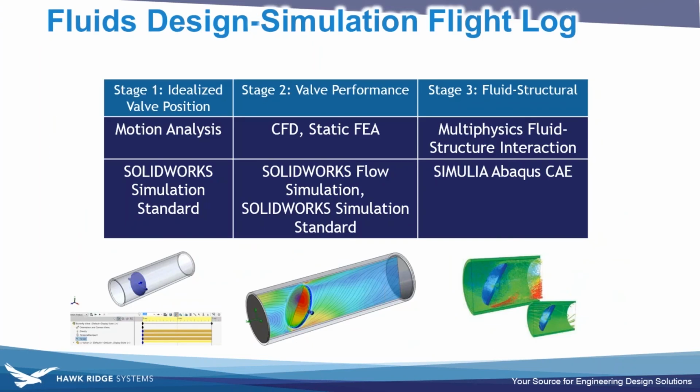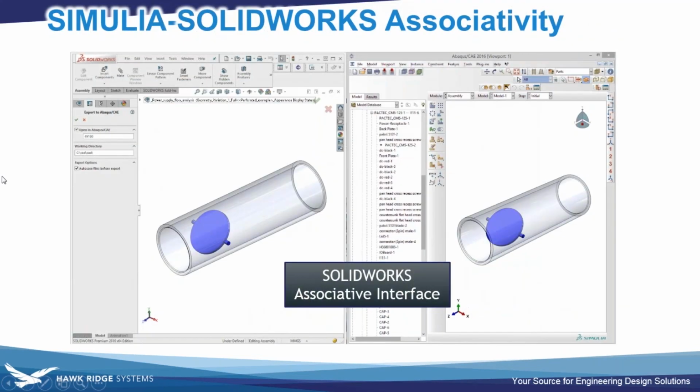And so in Abaqus CAE there are a variety of other options, of course, for the setup. Since it is a dedicated analyst tool, everything from different types of mesh elements, hex elements, in addition to tetrahedrons and other types of brick elements. And once we were to run that kind of a simulation, because we can enable both the structural and, for example, particle capabilities in the Abaqus solver, we could get this true, what we call FSI, or fluid structure interaction.